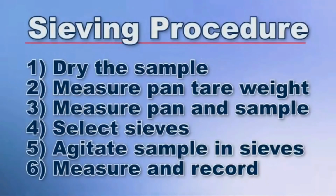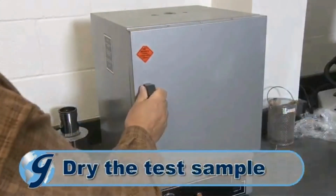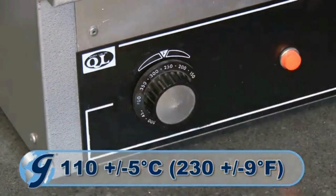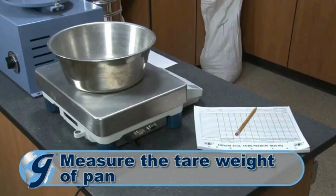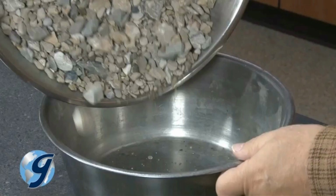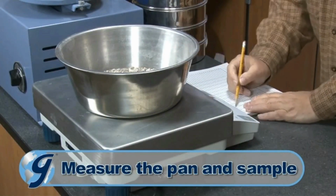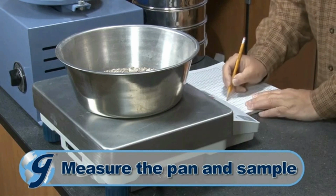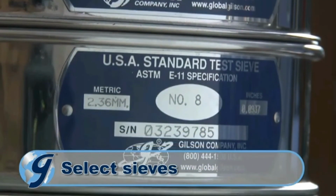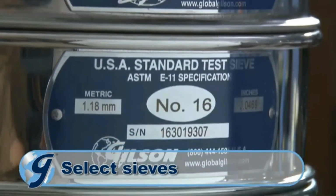The procedure for the standard test method for sieve analysis of fine and coarse aggregates: we first dry the test sample in an oven at a constant temperature of 110 degrees Celsius. Measure on a balance or scale the tare weight, or unladen weight, of your sample container or pan. Now place the test sample into the sample container and measure its gross weight. Next, select test sieves with suitable openings to furnish enough information required by the specifications covering the material being tested.